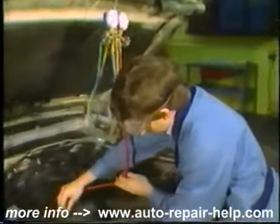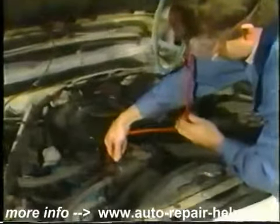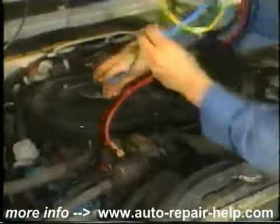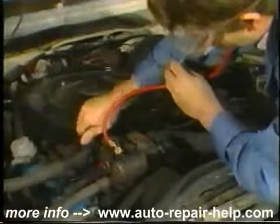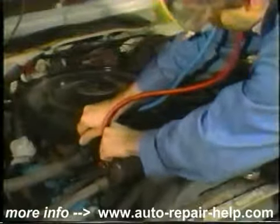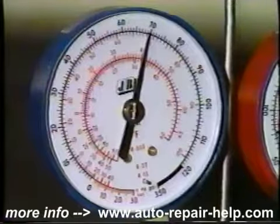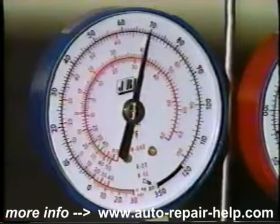Having completed the visual inspection, connect a manifold gauge set to the proper charging ports and bleed the air from the lines. The pressure reading should be equivalent to the ambient temperature reading, in this case 70 degrees Fahrenheit. This means that there is sufficient refrigerant in the system to make the test.